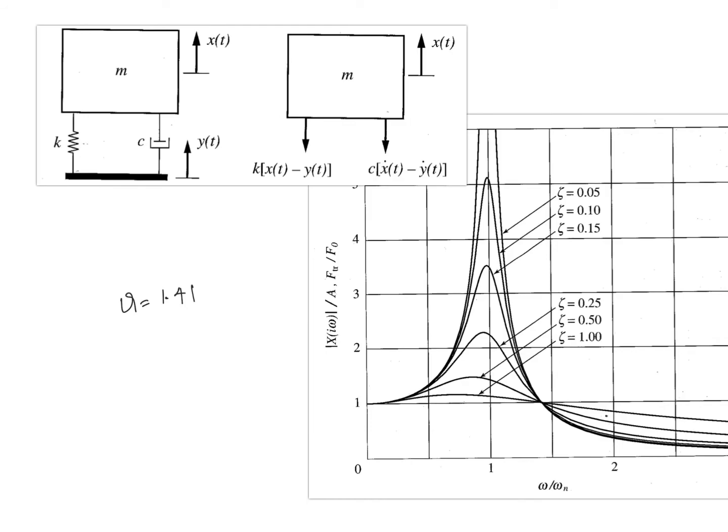For a value corresponding to that, you see, irrespective of the damping present in the system, your transmissibility ratio is always 1. And prior to that, if you provide more damping, it tries to bring down the transmissibility ratio, but as you cross this value over here, smaller the damping, smaller the transmissibility ratio. So these are a few observations that will come in handy in knowing more about this kind of curves.